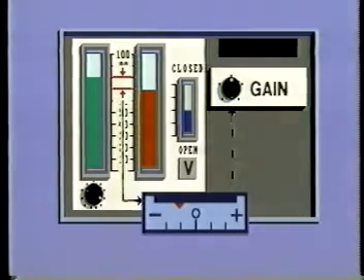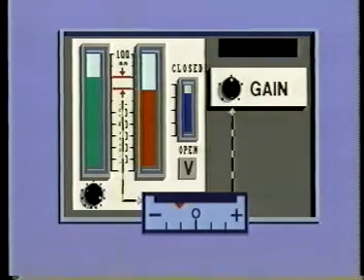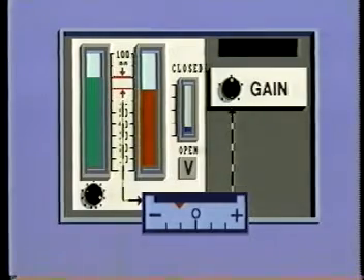The blue indicator within the controller shows the position of the valve, and the scale is graduated from valve closed to valve open. This allows us to observe the position of the valve whenever we want to determine the amount of steam entering the system.